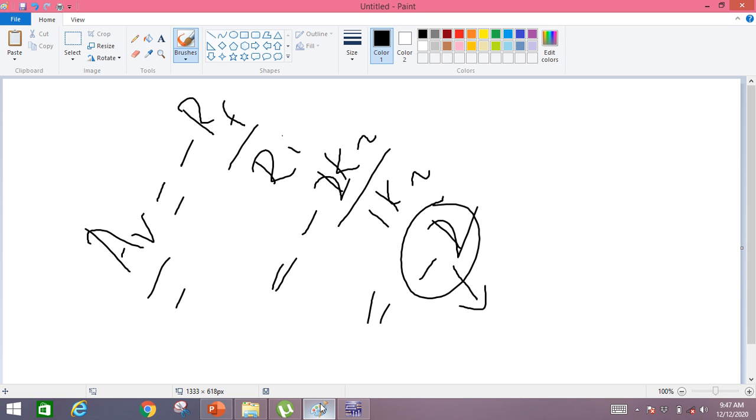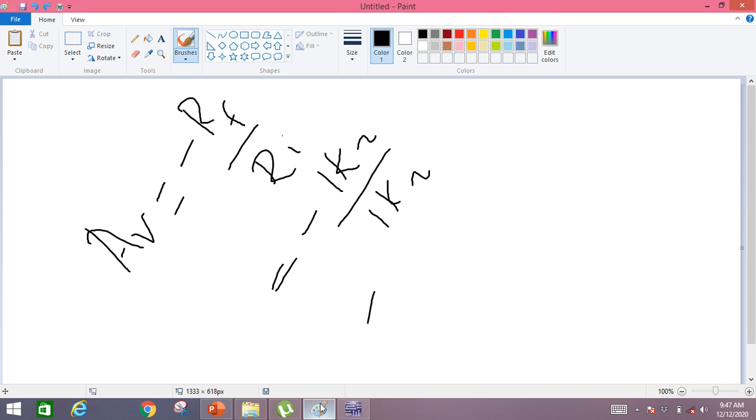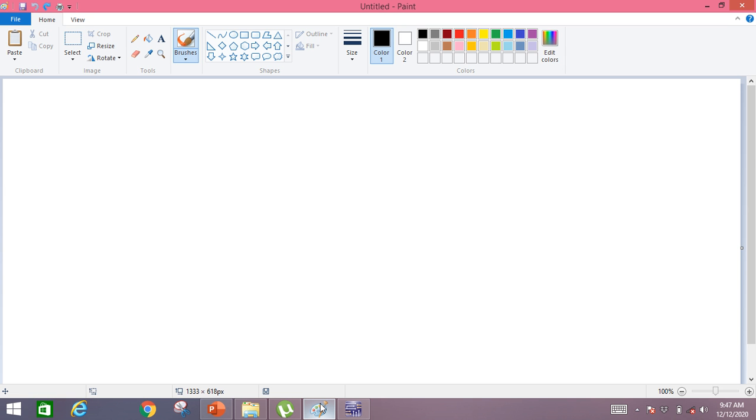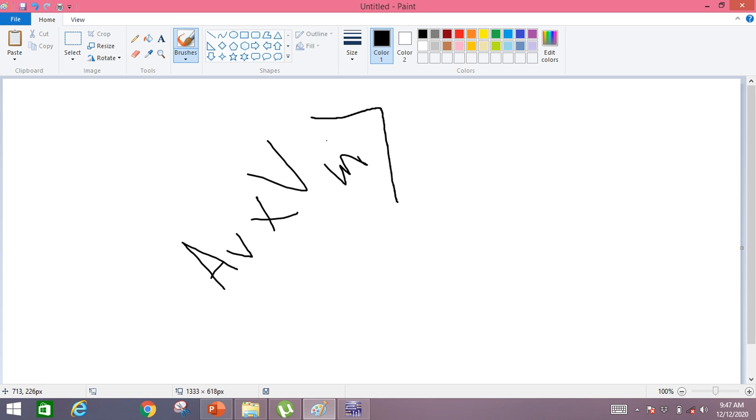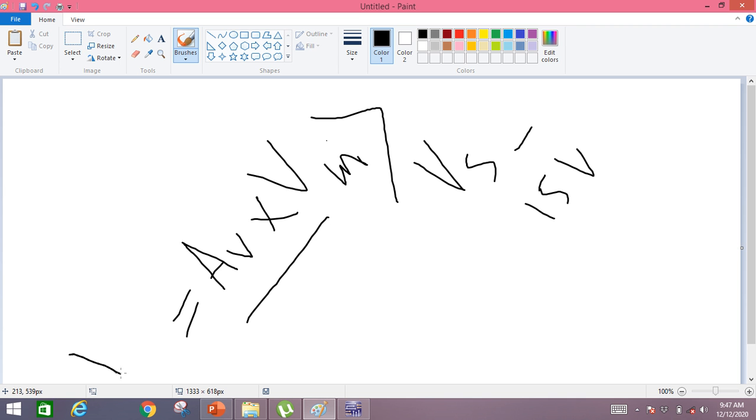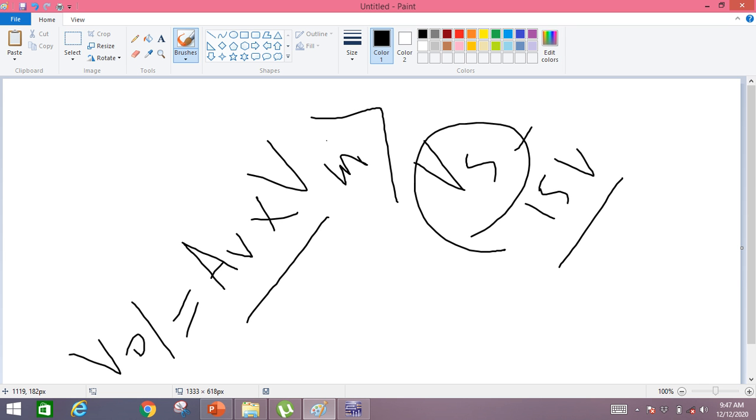It means that if the gain into the input voltage is greater than the supply voltage, here in this case the supply voltage is 15 volts, so the gain into the input voltage is actually the output voltage. So if the output voltage is greater than the supply voltage, the output voltage will be clipped at 15 volts.